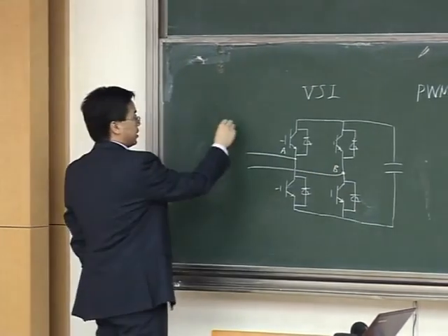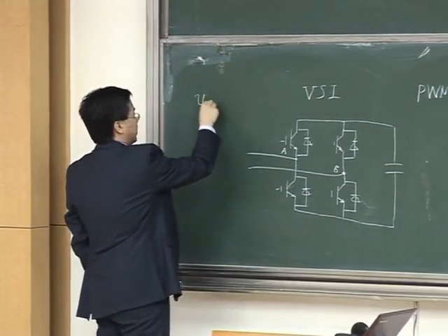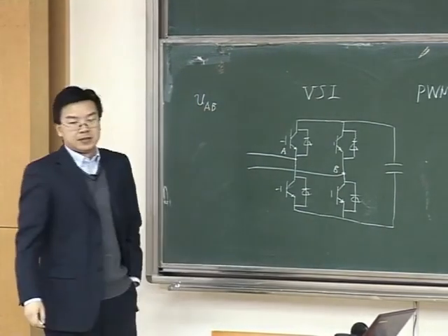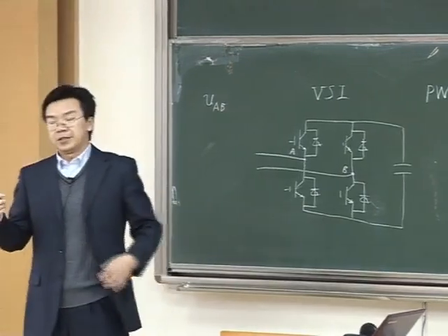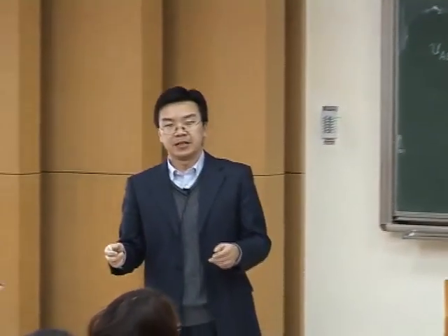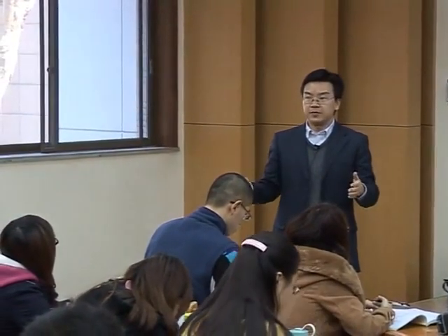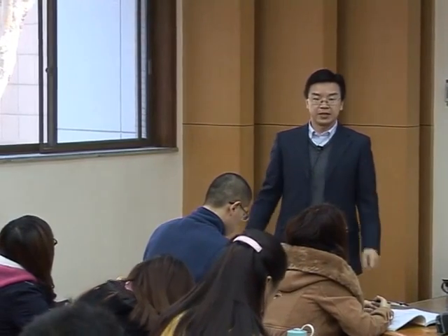This voltage between A and B, UAB, I can always make sure with PWM technique is very close to a sine wave with certain frequency and magnitude.